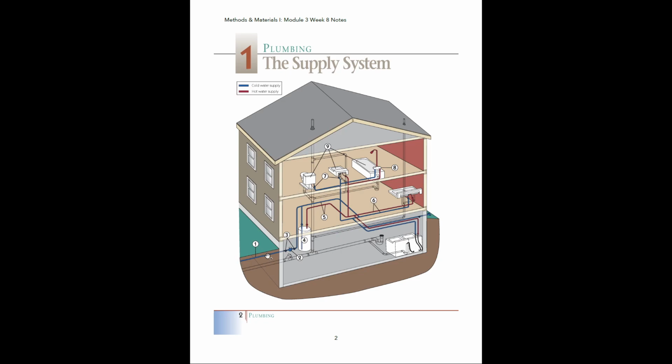Like I said, that could be a city water supply or it could be a well or something like that. Right? That is coming into the basement of the building here. And another thing about this is its location in the ground is going to be below the frost line. Okay, so there exists a thing known as the frost line. I think I mentioned it maybe previously, but the frost line is basically the point, if you're digging down into the ground, where water cannot freeze.